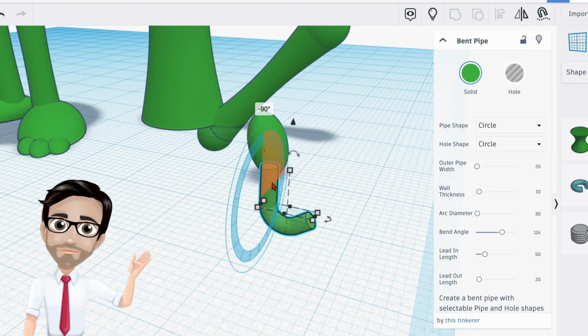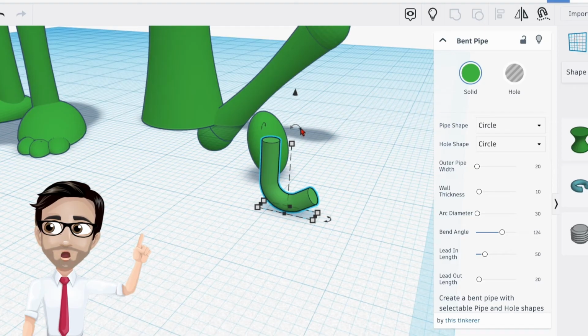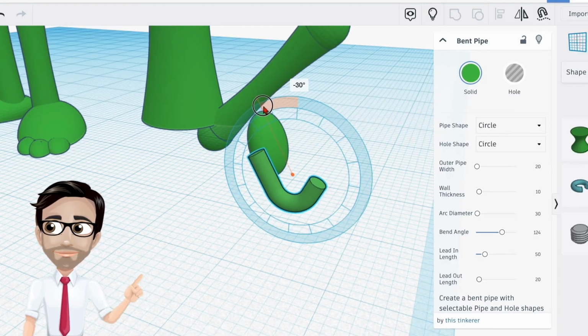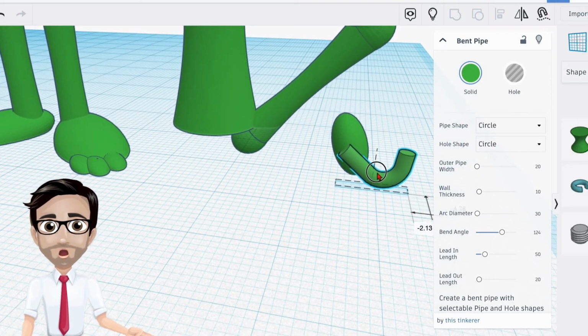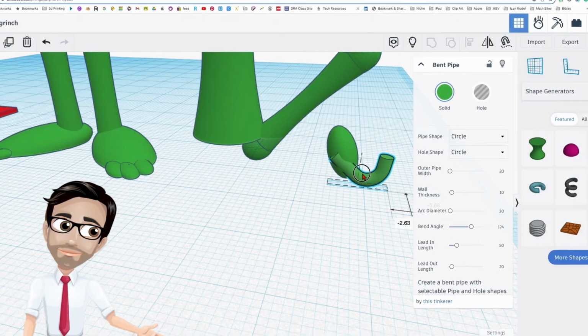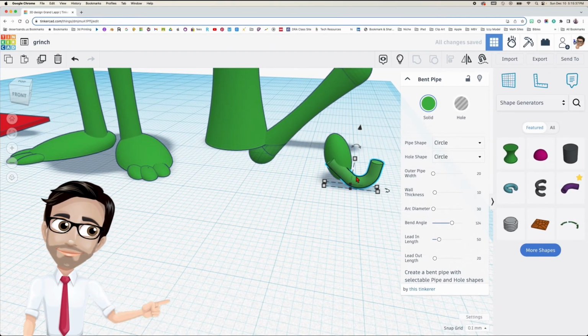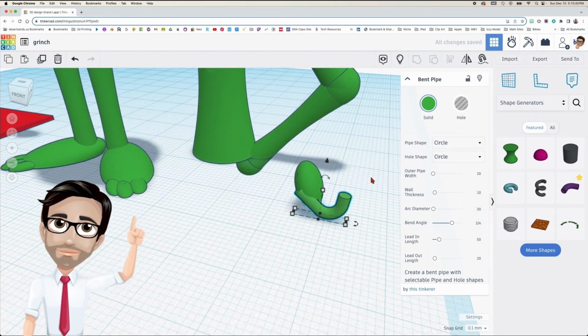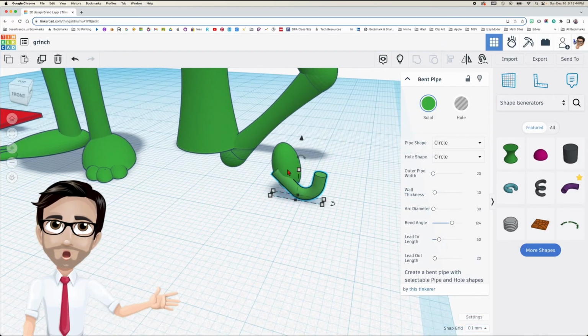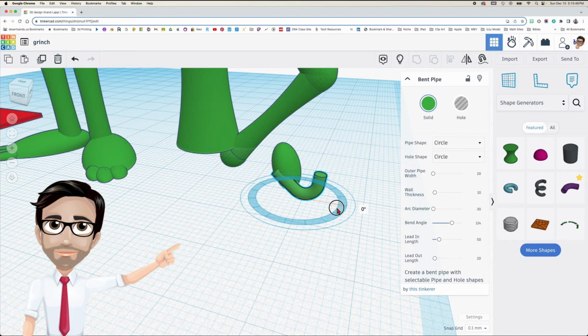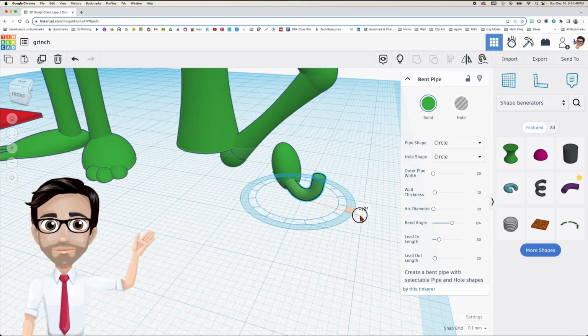I'm going to click the letter D. And then I'm going to rotate it backwards 50. This is actually what I was looking for. Negative 50 looks like. Yeah, negative 50. So let's go ahead and put that there. Oh, let's click D. There, now it's all the way down. Okay, now I'm going to hide this part of the finger by rotating it slightly and into the palm.